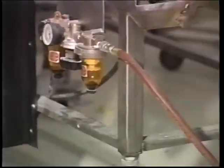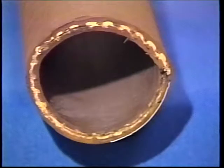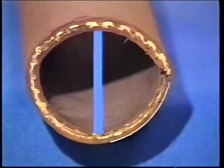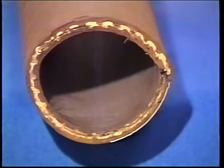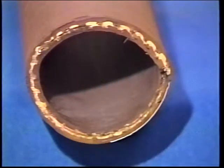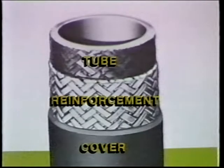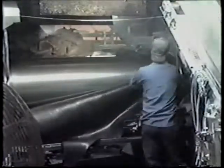Let's review. Hose is a flexible pipe used to transfer materials from one point to another. The identifying dimension of the hose is its inside diameter, or ID, and length. Other important dimensions are the OD and length. The three basic components of hose are the tube, reinforcement, and cover. The ability of hose to handle such a wide variety of applications is due to the technology of blending the tube and the cover compounds.